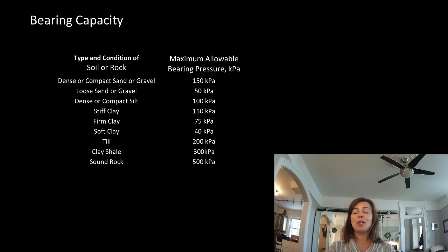Normally you kind of have a good idea of what's happening on the site. You might reach out to people who have done other projects nearby and take a glimpse at their soils report. You still need the final one for your site, but at least it gives you a heads up if there's anything surprising. Both of them, projects nearby, had no big surprises. Both of these projects, massive surprises on the soil capability on the site. One of them, we have to go down super far for fill. We cannot build on the soil that's there. We have to remove all the bad soil, build it up with good soil, and then build our foundations.